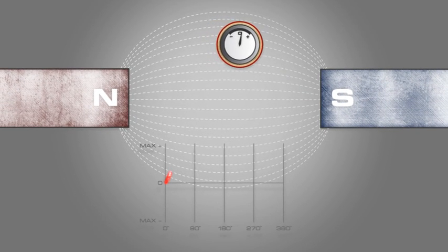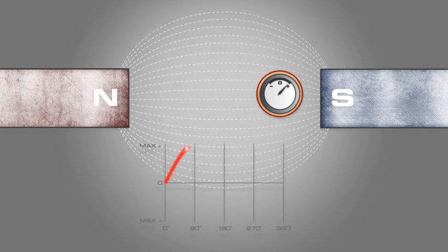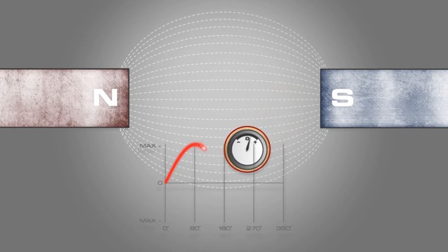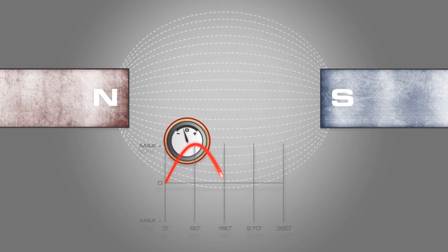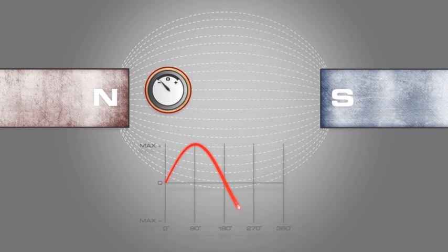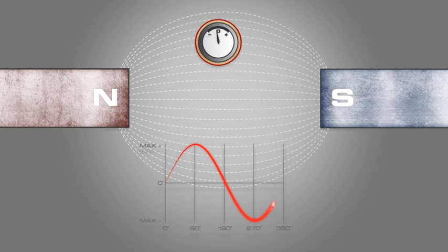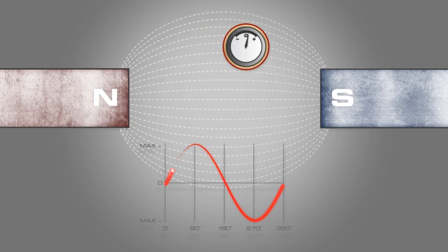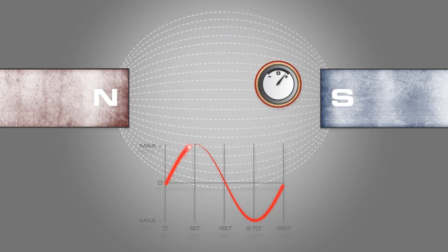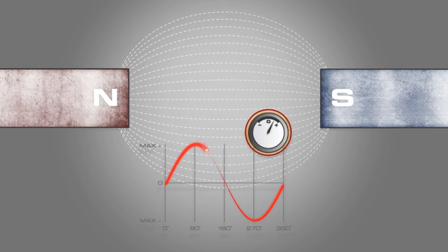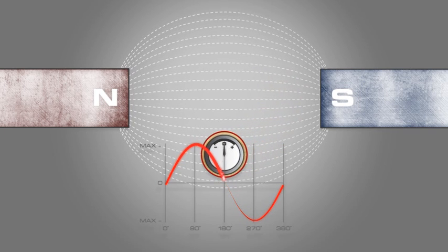Passing the conductor in a circular motion through the flux lines produces a sinusoidal waveform that corresponds to the location of the conductor. Sinusoidal waveforms are often referred to as a sine wave. Looking at the waveform, we can see how the current changes as we pass through the magnetic lines of flux. Take note that one revolution, or complete circle, creates one complete cycle for the sinusoidal waveform.